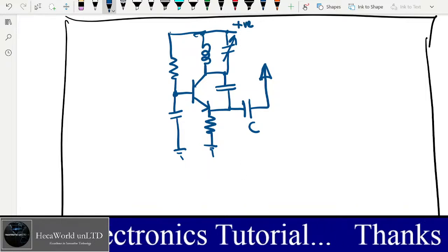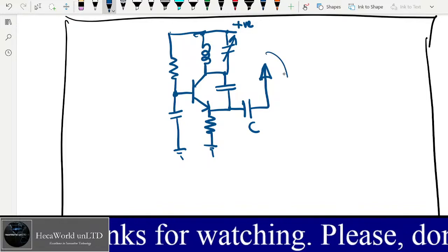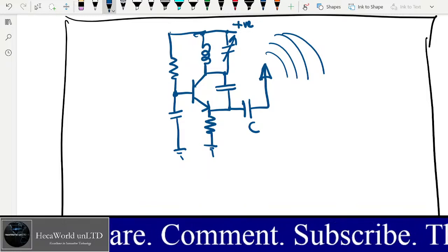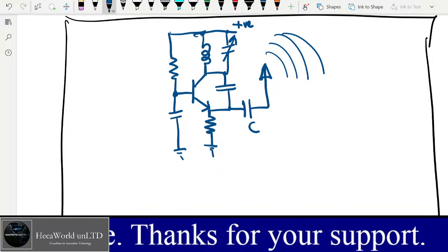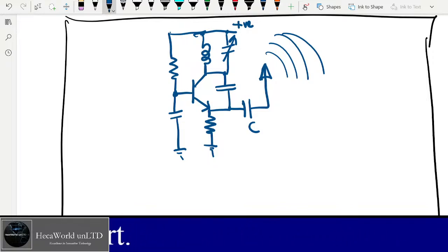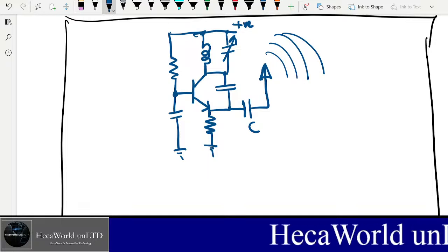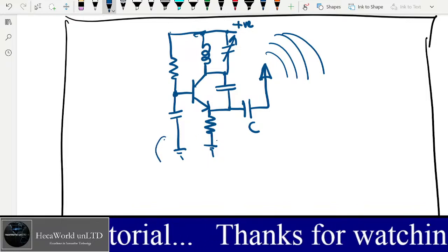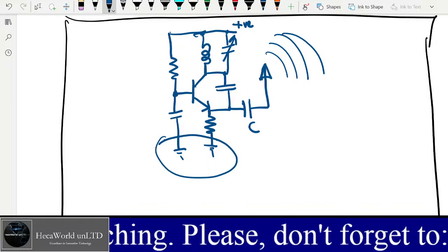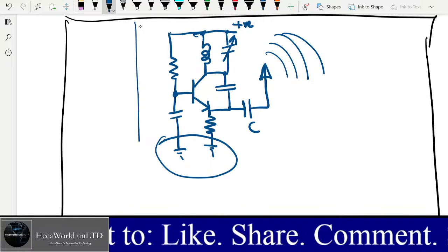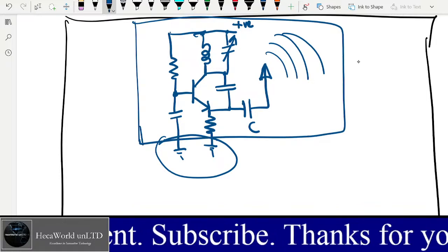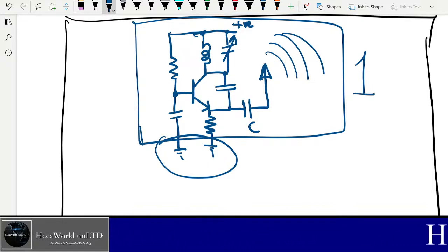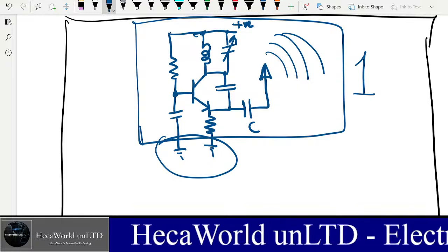Now, if you build this, this transmitter is always going to be transmitting as long as there's power, right? But the R433 was designed for intermittent use, so the battery can last much longer. So to be able to do what they did, instead of connecting these portions to ground, they connected that through another block. So this will represent number one in our block, and then number two is a very simplistic one. So let's just go and do that right now.